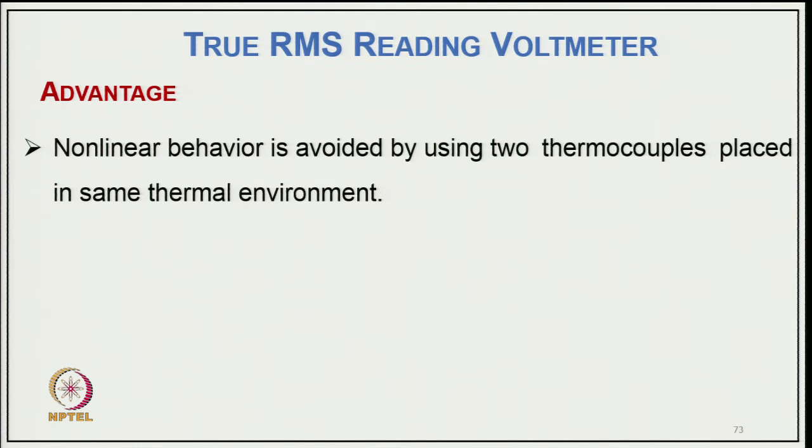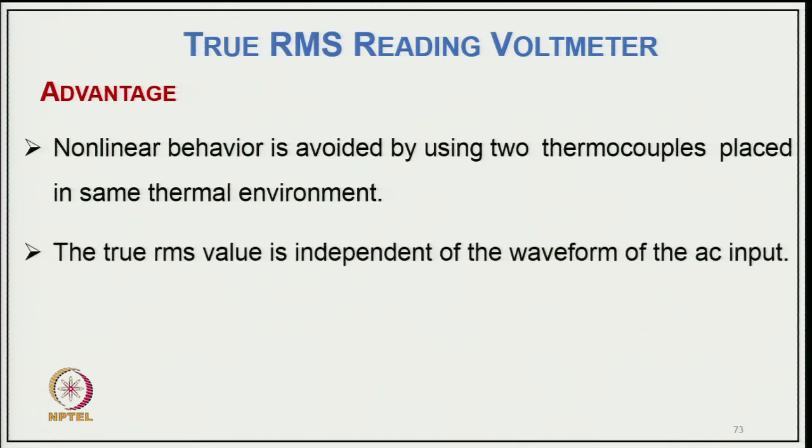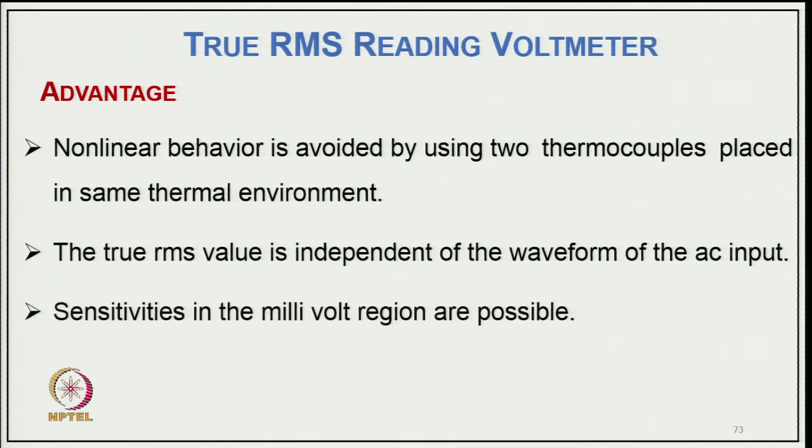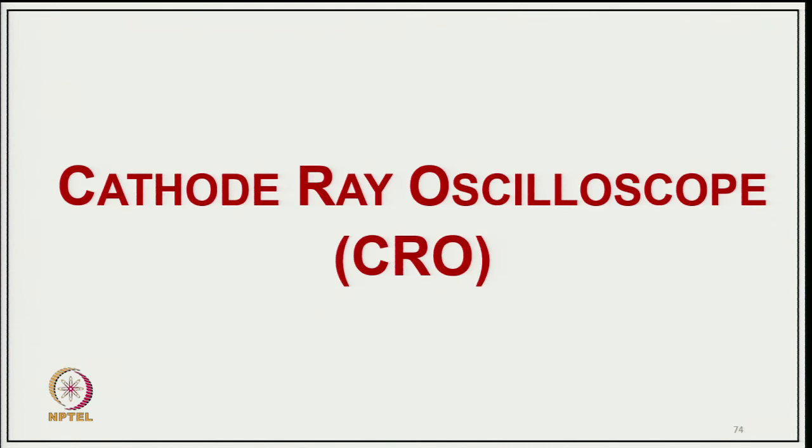The advantage is that nonlinear behavior is avoided by using two thermocouples placed in the same thermal environment, and the true RMS value is independent of the waveform of the AC input. Sensitivity in the millivolt region is possible.